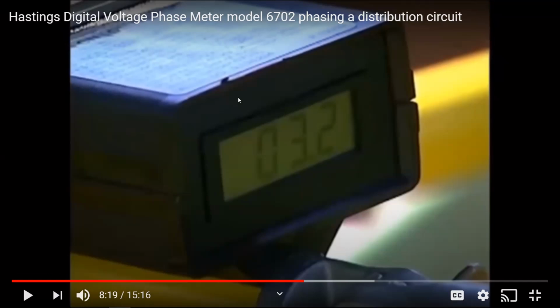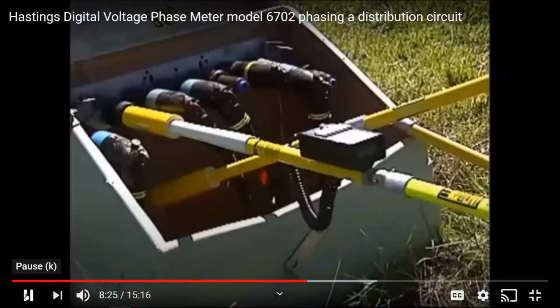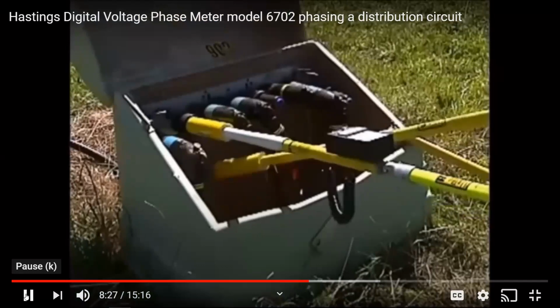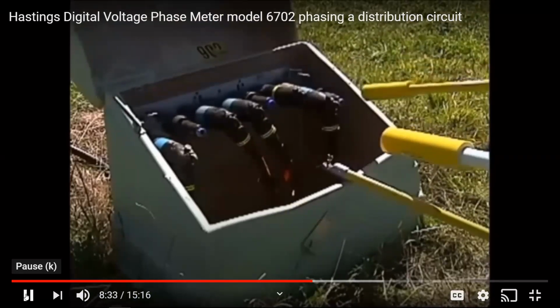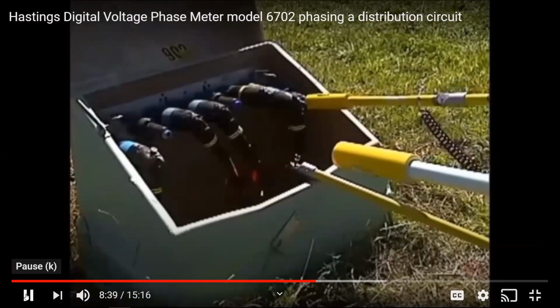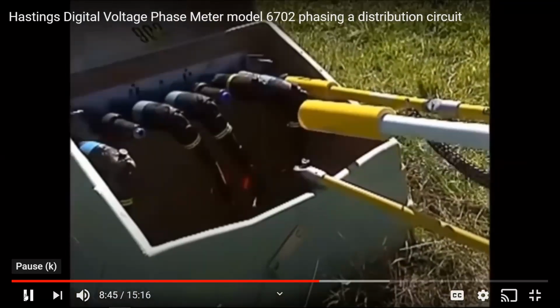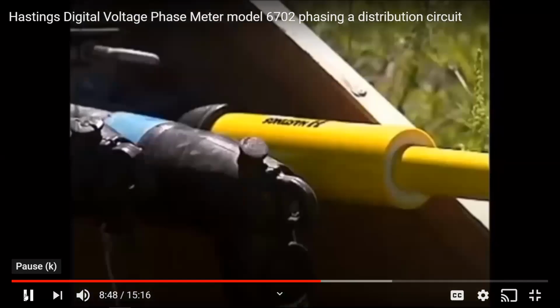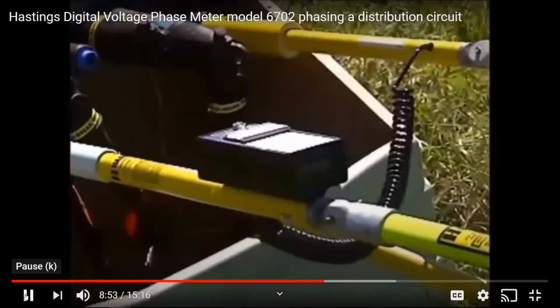He has gone from the primary conductor to ground with the other stick to measure a voltage. And that voltage is 3.2? The reading we expect to get will be between 60 and 70% of the line to ground voltage. And that's what we're seeing here on the meter. I'll put my non-metered end into the bushing for the cable that we want to test, so that when you plug into that energized bushing, we'll be able to watch the meter. What often happens is on a short run of very good cable, the meter reading is very short duration. So by watching it, you see the actual reading.